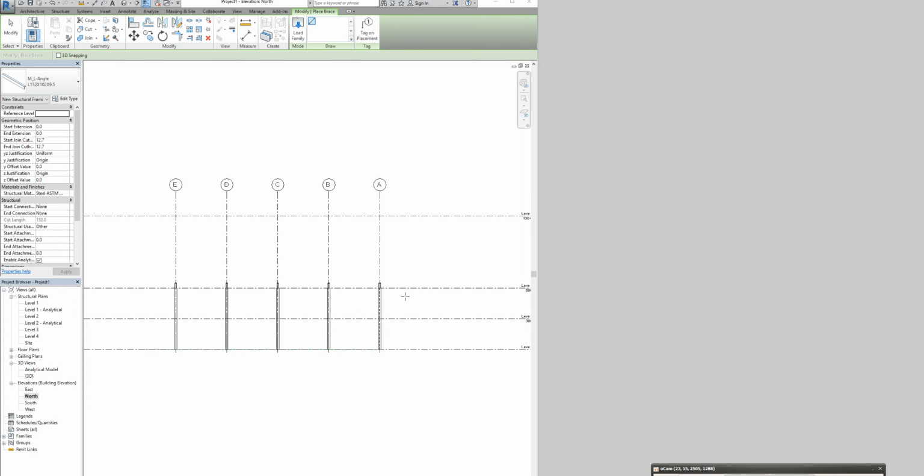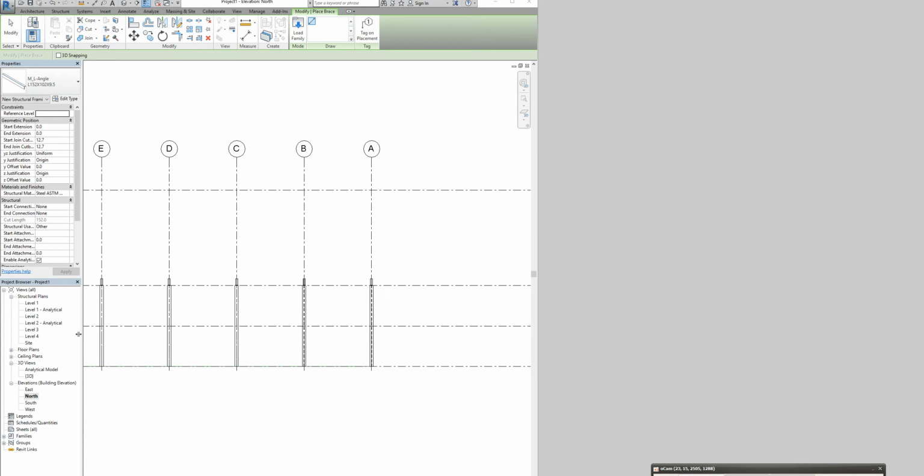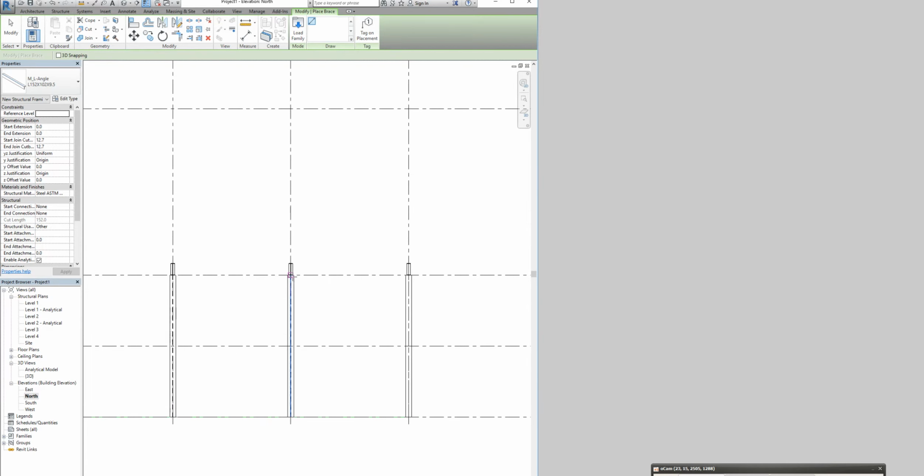Go to drafting area and create bracing between A and B grids. So we go here. We're going to start creating our brace. Be careful you don't take the endpoint. So select the endpoints of the columns, not the roof. So that's the columns here. The endpoint, not the midpoint, the endpoint is squared. So from here to here, and then from here to here. Finish.